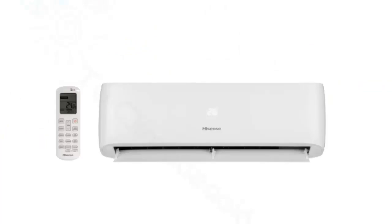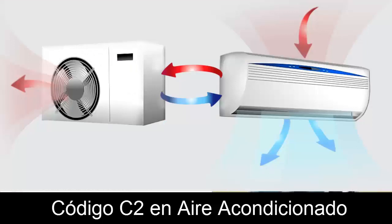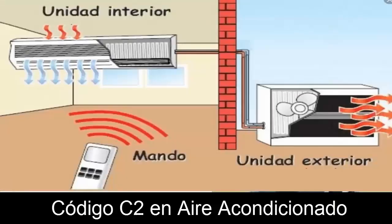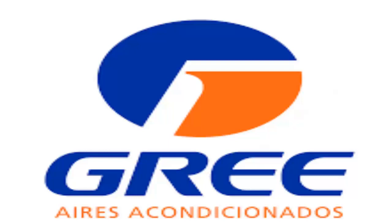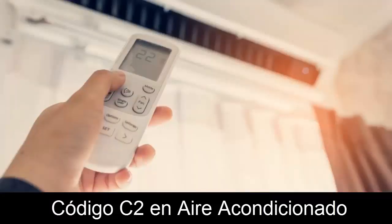3. Communication failure between the master control and the inverter compressor controller. This interpretation of the C2 code is used by the GREE brand. To try to solve the problem: A. Disconnect the unit from the power for several minutes. B. Reconnect the unit and check if the error persists.